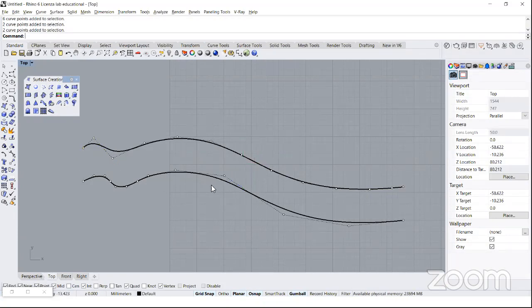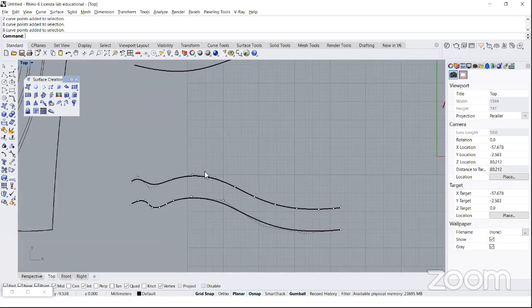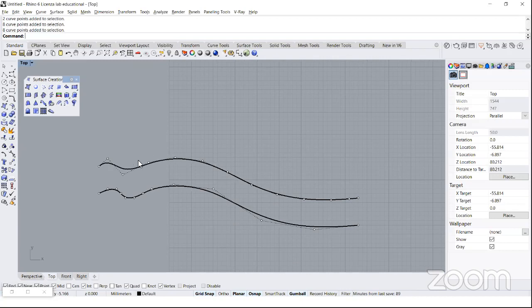While in our original configuration, original topology, we had more control points concentrated here and fewer control points in the second part. So with fewer control points, you see there is a smoother aspect for your curve, and with more control points, you can have a more wavy aspect because there is more local control. This phenomenon here is called local deformability of a curve. So in order to have local deformability, you must have more control points. This is important because if you rebuild the curves and you can reorganize the structure of control points, it also means that you are reorganizing the knot vector and the knots along this line.